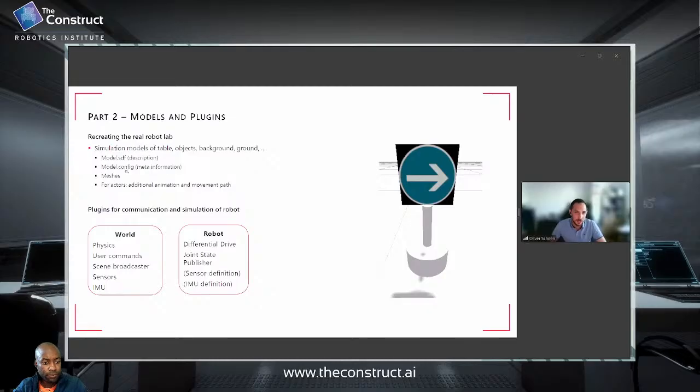First, it's the model SDF, so this kind of description file for the model, kind of similar to the robot description file, but just in this case for the simulation, and the config file, which gives a bit more meta information. Then what you can do is provide meshes, for example, pictures. Like on the right side here, this arrow, of course, you have to provide this picture information in order to display it.